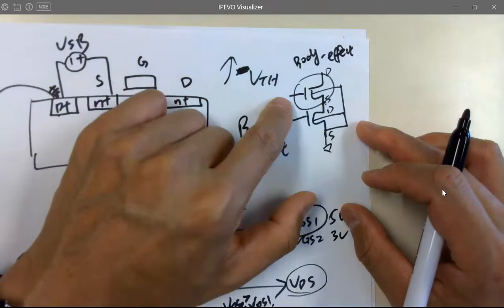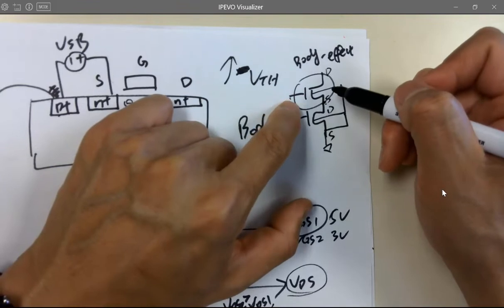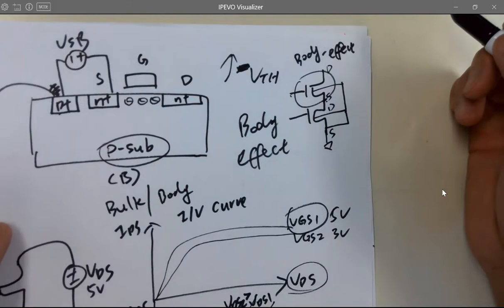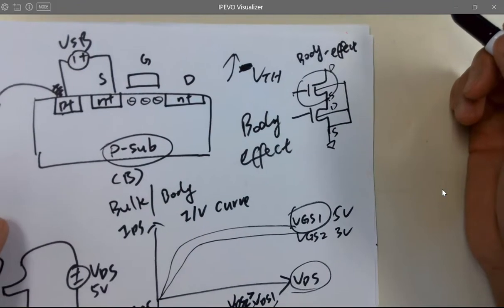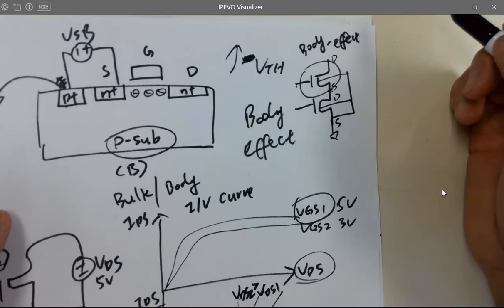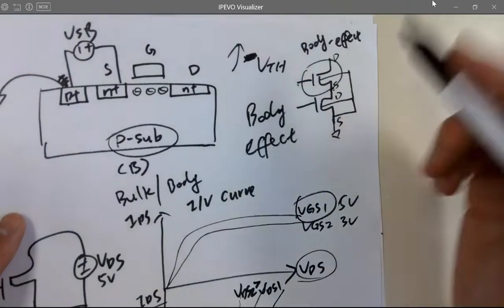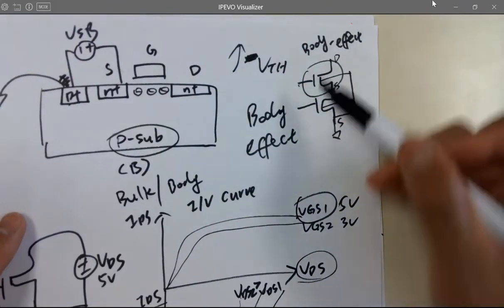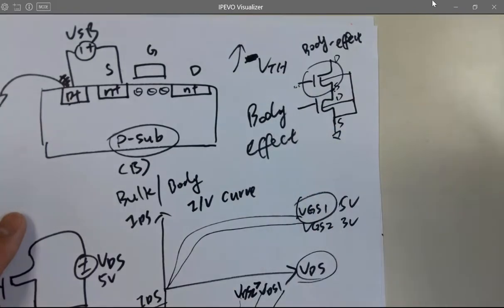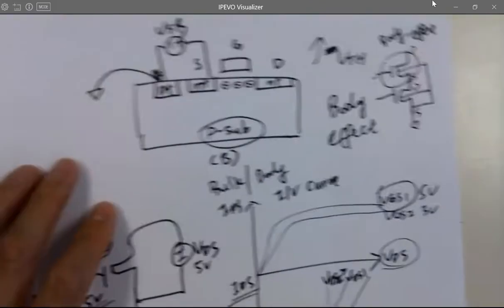You couldn't avoid that. You just increase the gate voltage to put more effort into turning it on. That's it. So when you're designing circuits like these, you usually just give your gates more voltage than they need, just to be safe. For this one specifically, you just need to know it. Whenever you are designing a circuit, sometimes you have to use a structure like that. You need to know that this gate voltage needs a little bit higher potential in there in order to keep this on. That's it.